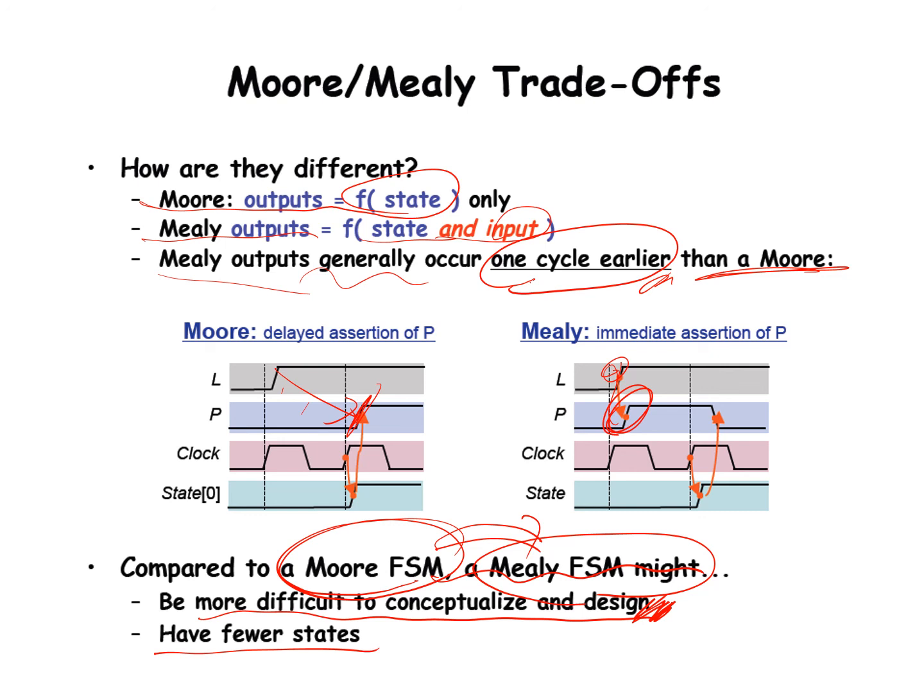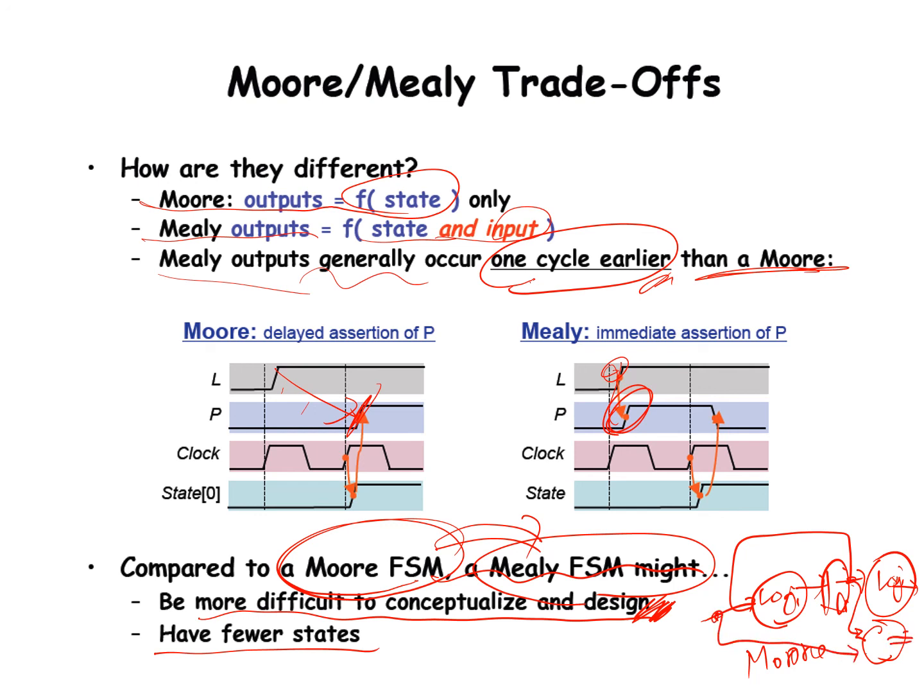Okay, so here: logic, flip-flop, output logic. This one is the Moore machine, right? If something is urgent or care must be taken, then take the state as an input and also the input to there, right? Like this. So going from Moore machine to Mealy machine is easier, right? It will be an easier transition because we have more states defined, so we can do more things.